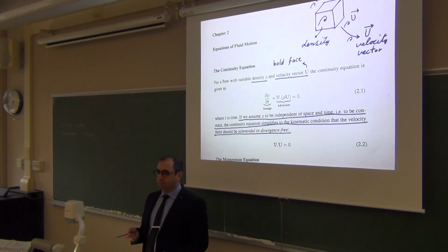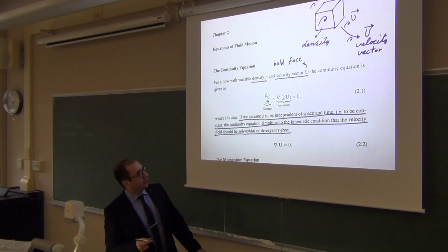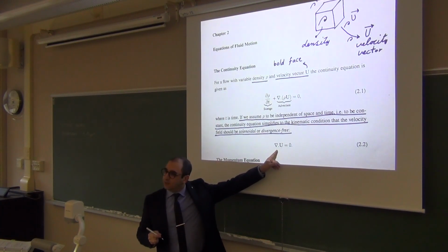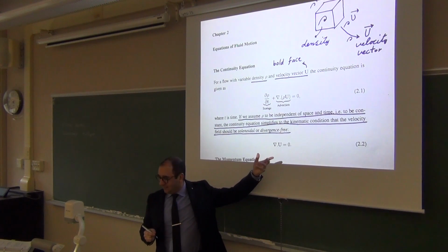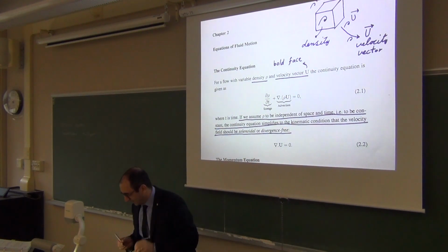Time. Mass. Right? When you say dynamics, there must be a mass in there somewhere, right? F equal to ma is a dynamics equation. But when you say kinematics, you only care about motion, only velocity, acceleration, and position, displacement are there. So by canceling the density out of the continuity equation, density is not there anymore. There is only velocity. So this is a kinematic condition, right?